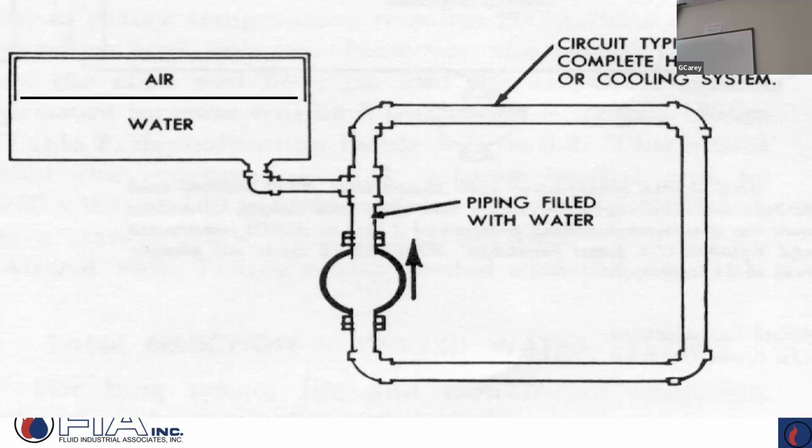So he says, okay, take the boiler away. Now say you draw in a fill valve, just what we talked about, pressure reducing valves, and you opened it up and added more water to a system that's completely filled with water. Where's the only place that additional water could go? Just like we said, it would go to the tank. And then going to the tank, it would change the ratio of the volume of air, which means it would change the pressure. So if I heat the water or I add water, which means I can change the volume of air, I can change the pressure in the tank.